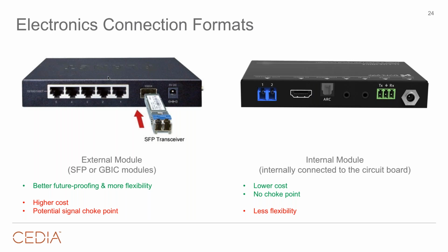Now, the downside of that is most SFP modules come in 1 gig or 10 gig formats. At least in the market today in 2018, the most cost-effective modules for the real world are 1 gig or 10 gig. Now, if we think back to that chart we looked at, we know that 4K 60 4:4:4 HDR goes up to 18 gig. 8K goes up to 48 gig.